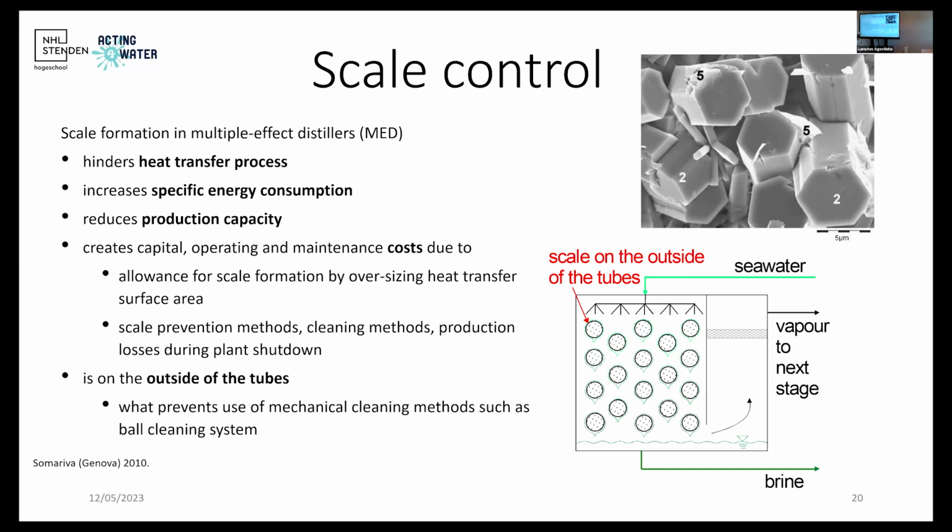I don't know if you remember the last time we discussed OPEX and CAPEX costing in membrane systems and thermal systems. The thermal systems do have a chemical cost, but smaller than the membrane cost. But these chemicals are mainly, I repeat myself, to control scaling, but also anti-foaming, because foam formation, especially due to the showers and large surfaces, could also decrease your efficiency drastically or create contamination passing through the limits.